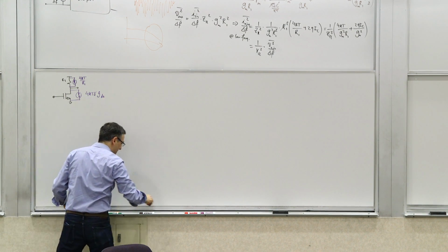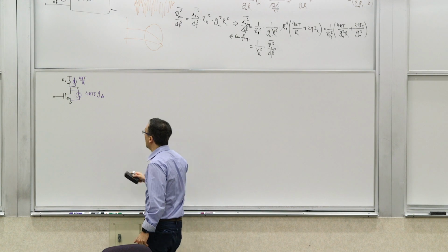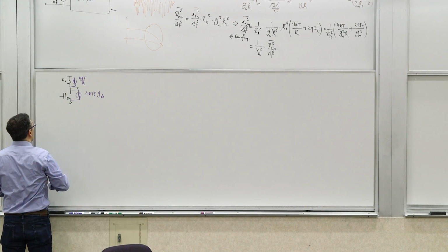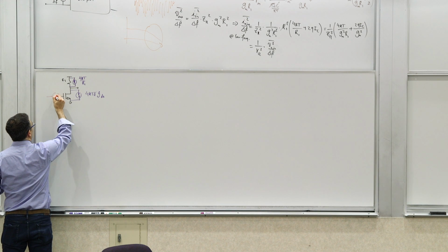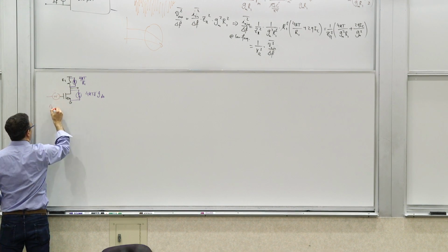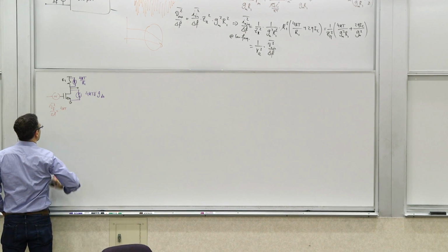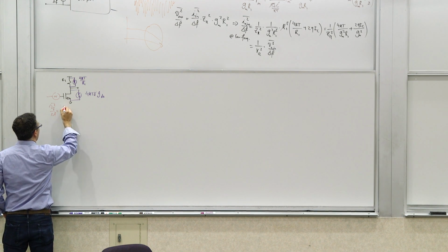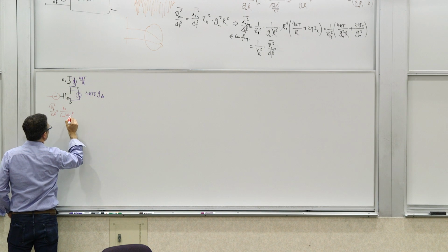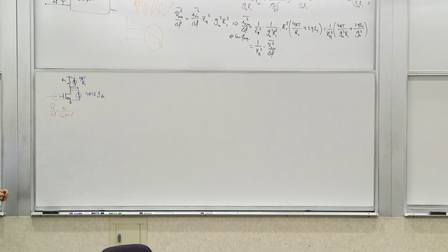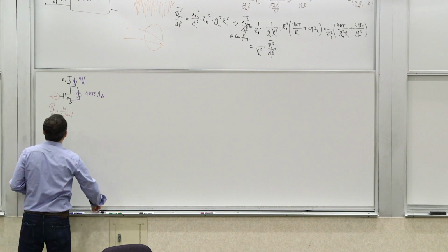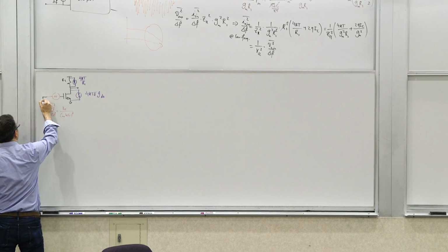And then we also have, let's say, the flicker noise of the MOSFET, the 1 over F noise, which we model in this case as a voltage source at the input, which would be, not 4 kT, KF over Cox WLF. So you have these three noise sources, and you're trying to determine what is the total input referred